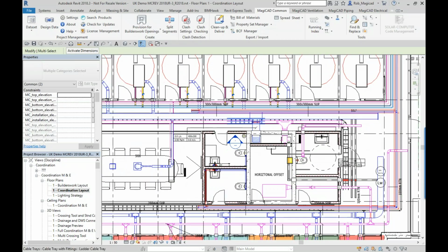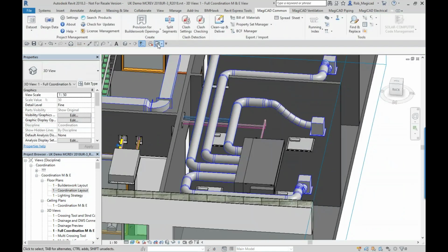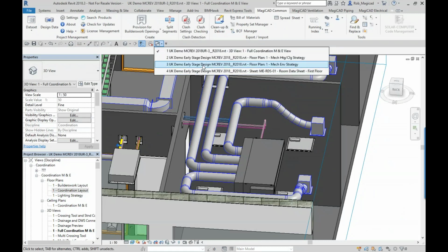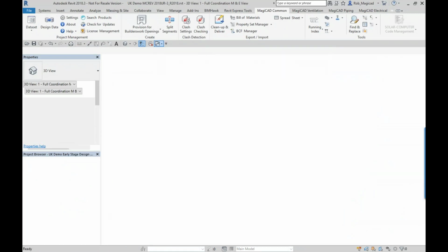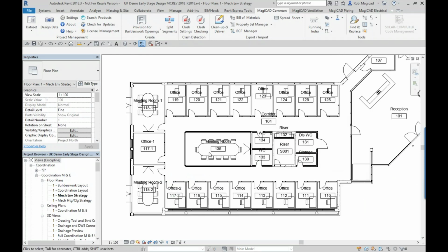The next tool I want to look at is the spreadsheet import-export function. There are some others available on the market, in app stores and things like that. Generally, the ones that I've seen have to use Revit schedules to export to Excel and back in again. But this MagiCAD one doesn't need to do that. It actually imports and exports directly from the model rather than from a schedule, so you don't need to create a Revit schedule to do this.